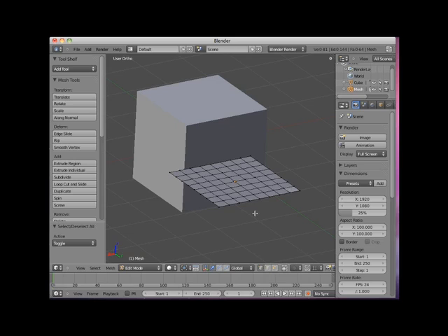To use the Circle Select, I'll press the C key. This displays a circle that can be expanded or constrained by scrolling the center scroll wheel. To select vertices, just place the circle over the vertices and left-click. This will select any vertices that fall within the circle. You can continue to add to the selection by left-clicking again. Right-clicking escapes the Circle Select. I will deselect the vertices.